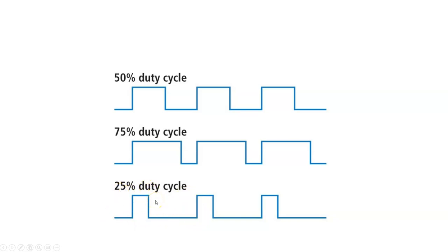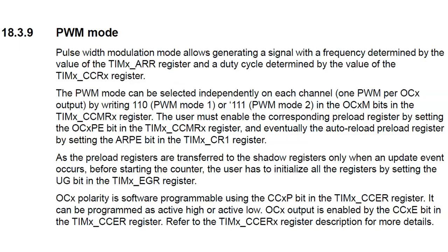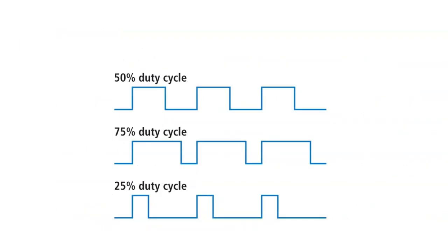So this particular kind of signal, where you can use a digital signal as a power proxy of an analog signal, is called pulse width modulation. We're basically changing the average value of the analog waveform by changing the width of the pulse, and we're modulating that to get the different analog values, and hence the name pulse width modulation.